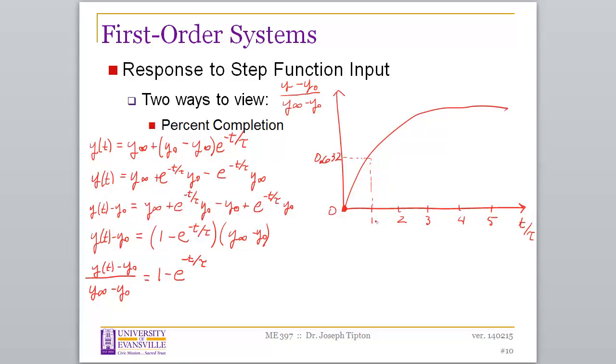Okay, so after one time constant of time has passed, the system has responded with 63.2% completion. It's still not passing all of the input signal. Note the full step occurs about 4 or 5 time constants after. By the time you've gone to 5 time constants, you end up with just about 100% completion.